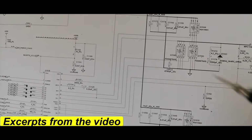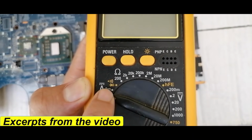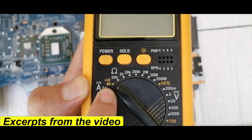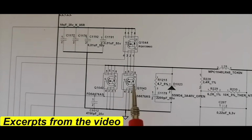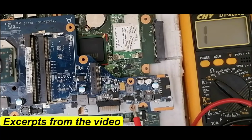We can even check the MOSFET using the multimeter. To check the MOSFET using the multimeter, we should always select the diode option. Why? Because simply the MOSFET contains a diode inside it. As you can see, this is the MOSFET, and here we have the diode between drain and source.